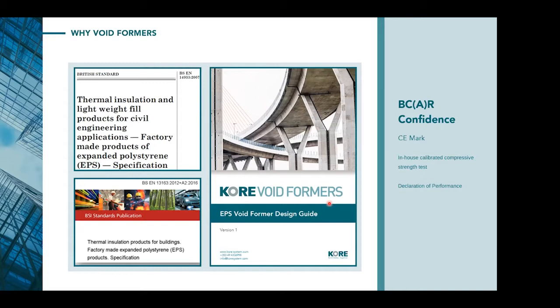Testing, and giving people confidence in the EPS and proving that it's going to do what we say it's going to do. We test all our EPS materials in-house, but we manufacture to various EN standards. The main one that people would probably be more familiar with is EN 13163. This is around the thermal performance of EPS. There's a lot of information stated when we test that, and that's stated in our declarations of performance and allows us then to have our CE marking for the material.